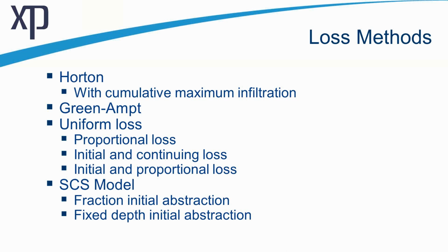But where we start with a high initial infiltration, and that then weans its way down to that ongoing infiltration rate, which, depending on the catchment characteristics, may be as low as 1 or 2 millimetres per hour ongoing. And that's the kind of information that's definitely important in those long duration sunny day type flooding situations. So Horton's method is definitely a loss method that can be used as a continuing loss method.